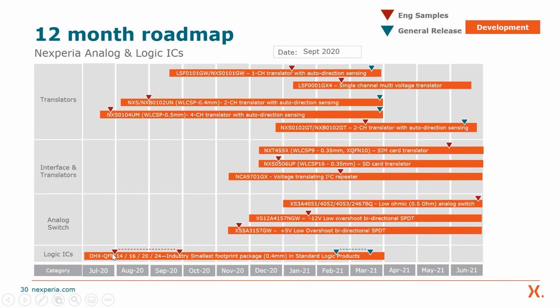Also shown here is a family of logic devices in different package formats. In this case, it is DHX QFN, which is the industry's smallest footprint, with a 0.4 millimeter pad pitch.